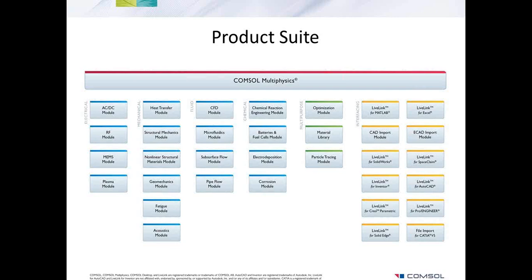If you do not want to resolve the layers, let's say for example they are really thin, and you have a lot of layers, then you can again use a homogenized approach. You can just consider the whole thing to be one bulk material, providing you with one bulk displacement when you excite it. So that could be an alternate approach if you're not really sure how many layers are really there.